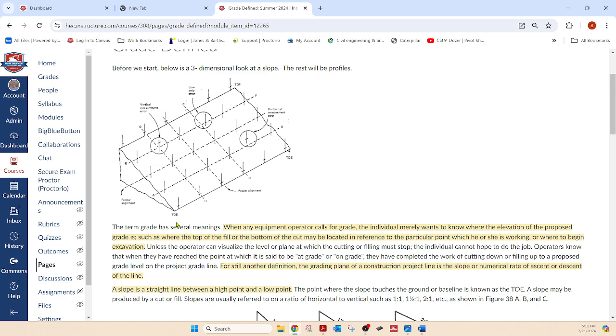So when we come in here and build this fill slope, all this area is flat right now. The first thing we'll do is bring a scraper down here, and it'll drive across here and dump a lift. That's a scraper-wide mass of material, and he's good enough.